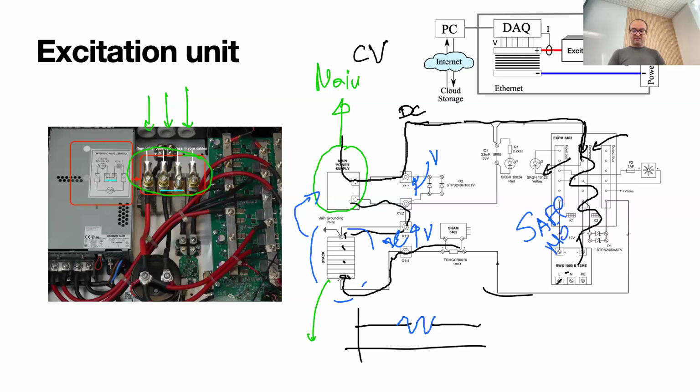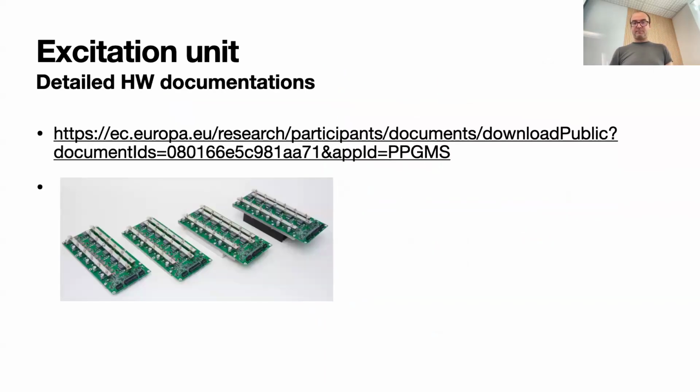Safe mode because it says that the stack switch, we are expecting an electrolyzer, and now we are having fuel cells, so some current is coming through, although minimal. So you have to reboot it. There is a procedure how to do it. There is nothing will break, but the unit will go into safe mode. And this happens only during startup if you're not careful enough or something happens. Luckily enough, everything is safe.